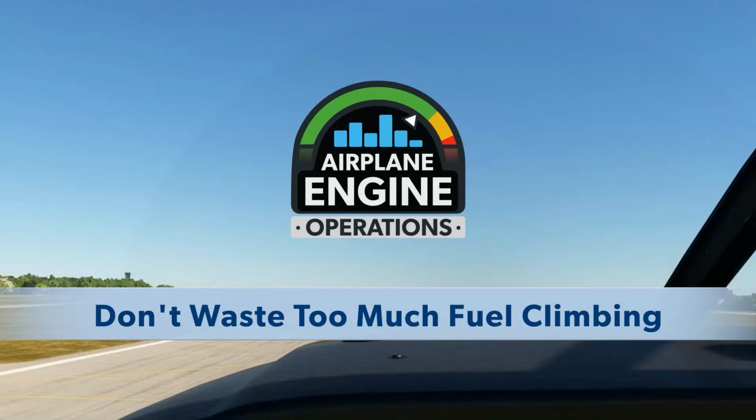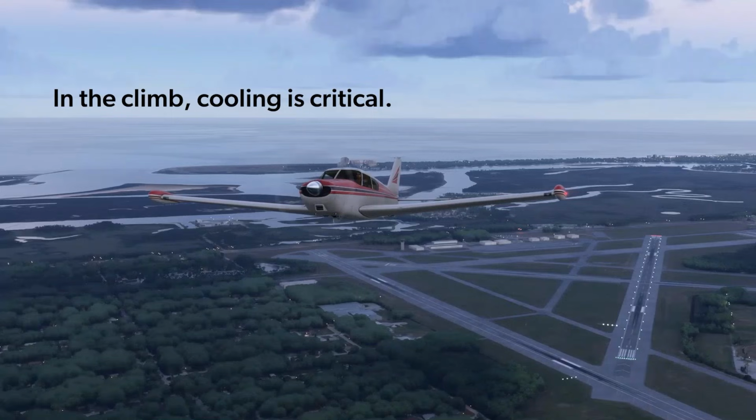All right, so our next example is how not to waste too much fuel climbing. Full rich at sea level, full power is essential. It's just what you have to do to keep the engine cool. But it is okay to lean really anytime above that. But when and how? First of all, it should be said that the most important thing here is engine cooling. This is the critical thing. We're operating at high power, low airspeed, not as much cooling airflow. And so maintaining the temperatures at a reasonable level is really your top priority in most cases.